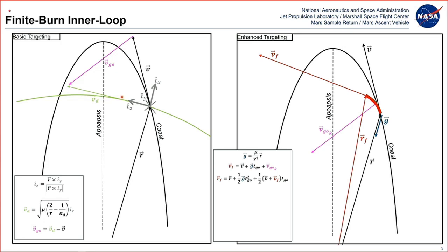But the next thing we do is we take one iteration of our velocity to go, which you can either use the iteration from your impulsive decision, or you can just start by priming velocity to go with the zero vector. Either way, the algorithm has been proven sufficient throughout the entirety of MAV's operating environment, where whatever you want to initialize velocity to go to, you'd be fine. But using velocity to go and using some pretty simple linear dynamics, you can actually come up with an estimated final position and velocity after you perform this maneuver.